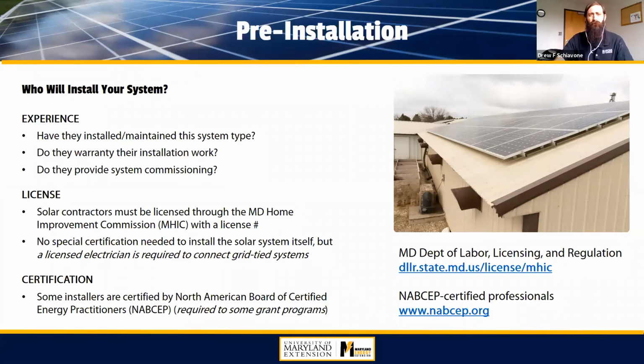And we'll talk about what's included in the bids momentarily, but if you're looking at various contractors, you want to look at their experience, if they're a reputable company, if they have experience working with the type of system you're interested in installing. If they've only worked on rooftop systems, you may not want to hire them for a ground mount system. So specific equipment and things like that. So do your research, find out if they're well equipped to do the job that you've hired them for.